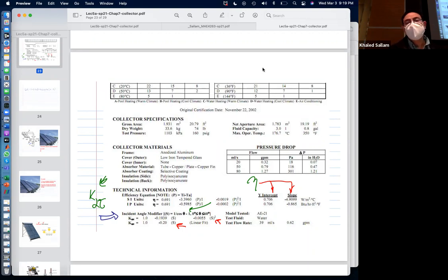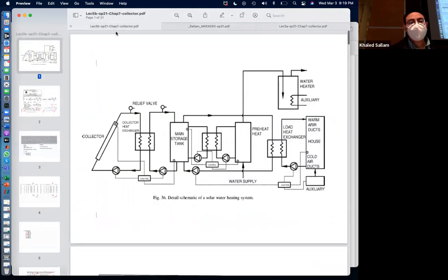Very good. So what we did is the calculation of one collector. Now, we need to think about what if we have a lot of them, how do they function? And also, that level of calculation per day, per hour, where is the sun, what's the incident radiation angle, what is the key, what's the efficiency? This is like torture for a big system. If you're designing a big system, you cannot do that for every single hour. So we need another way to calculate, like a rough estimate, how many collectors we need.